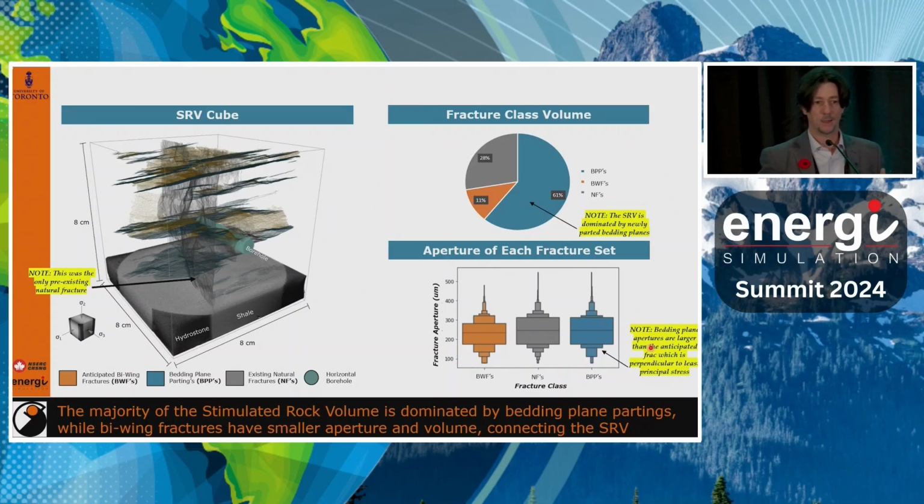One is a natural fracture we knew was there. Another was parting of bedding planes that will split during hydraulic fracturing. And then the so-called hydraulic fracture, what you were expecting, opening against sigma 3. Oops, what does it mean? It means that the others were not opening against sigma 3? Exactly. So the key was that most of the fractures that we measured, almost 90%, were not actually opening against the minimum principal stress, as we learned from the book.